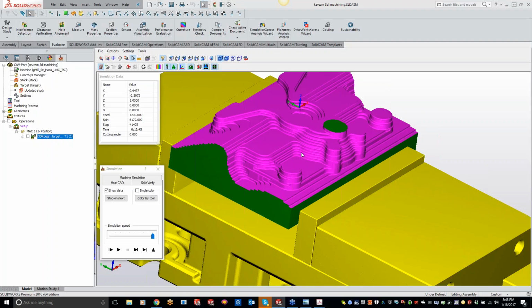So it's one huge advantage using iMachining over everything else. And I'm not comparing to SolidCAM, any of the other CAM companies out there. What I'm comparing it to is like HSR or HSM or HSS, which is the same module that all the other CAM companies use. That scallop is going to be the same scallop height throughout the entire cut using 3D iMachining.